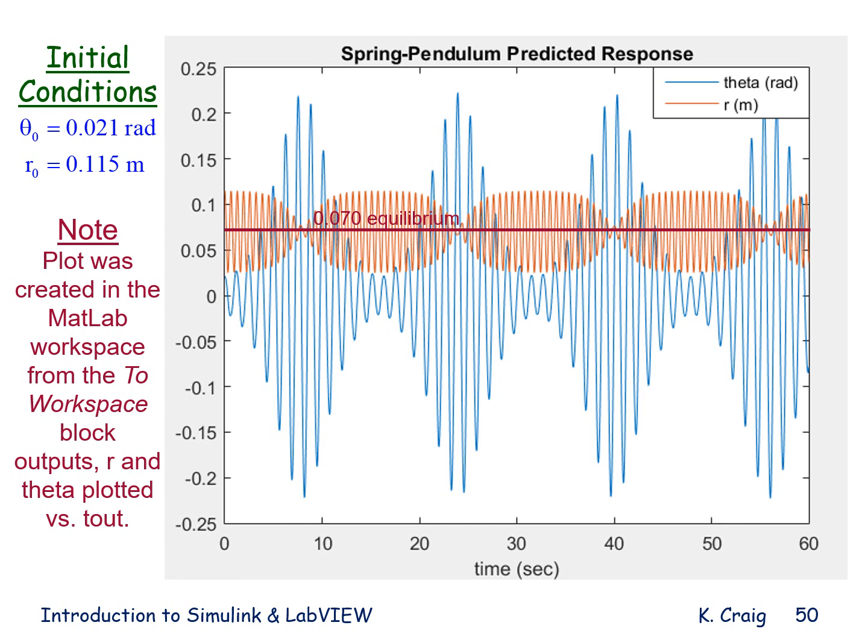Even if you could pull it exactly straight down, because of asymmetry in the system, because it's not perfectly symmetrical in terms of the spring and the mass, there will be some slight difference, and that slight asymmetry will cause it to go from spring mass motion to pendulum motion and back and forth, also with very distinct transference of energy from one mode to the other.